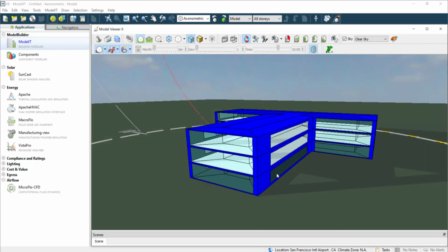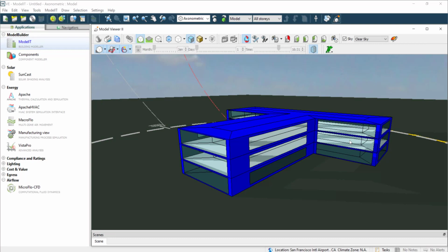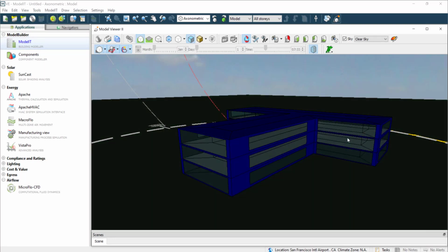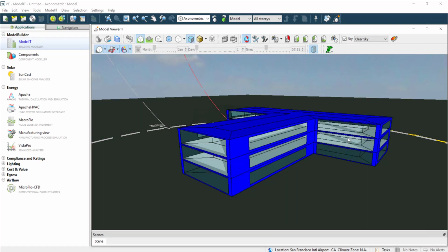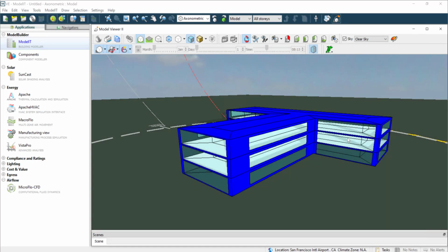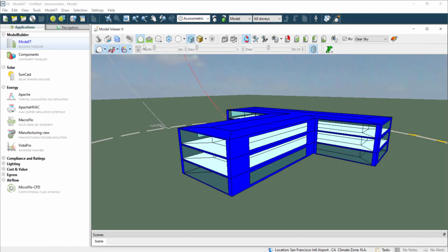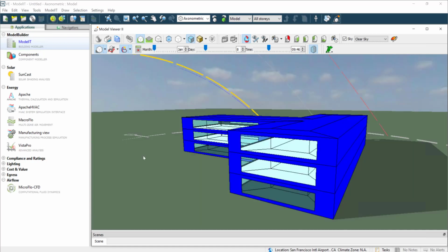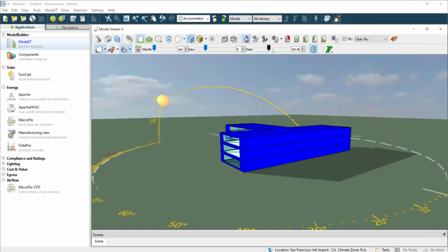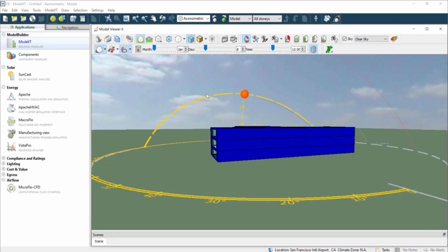There's even some self-shading on this building occurring. That's going to help track solar radiation, therefore solar gains after you know the SHGC of the glass, cooling loads, the energy consumption, and so on and so on. Just going to pause that animation now and you get the idea. Hopefully it makes sense. Of course, you can make that image look like anything you wish, and move on.